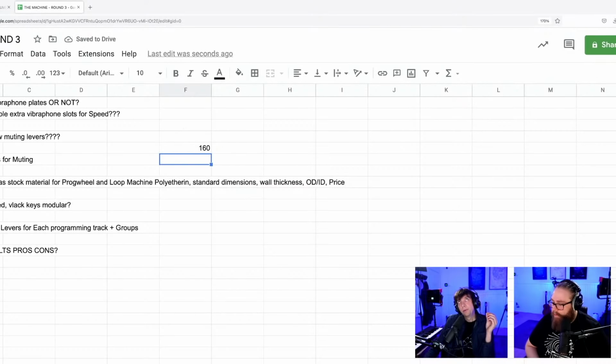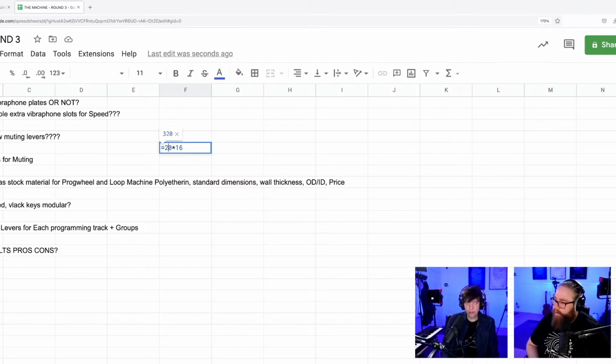So you have to buy from somewhere a belt pulley which is like 80 centimeters big with 160 teeth, and then you have a very, very tiny gear on the first, so 10 is too little. So I would increase this to at least 20 teeth on the first gear. So you need a belt pulley with 320 teeth, and I don't think that exists.